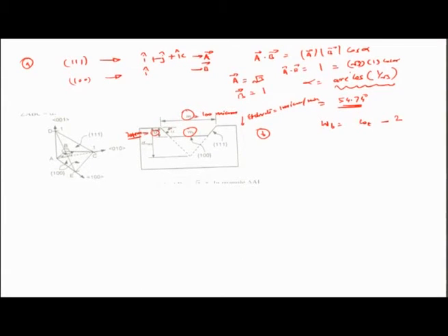So with d on board here, we know that this particular distance, which is from one end all the way to the projection of the lower surface onto the top surface, this x right here, is represented as d divided by tan alpha, and so you have such x in both the directions, x here as well as x here, and geometrically we can say that WB comes out equal to WT minus twice d by tan alpha, and that's how you look at WB.